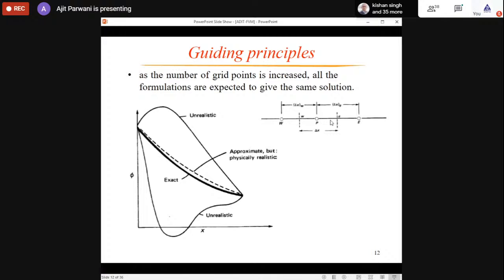So this surface is common to the adjacent control volumes. It means that the flux that passes from P to E should be received by E. That is, the flux at this surface should have a single value, not a double value. There should be a consistent flux at surface E, because it is common to both the control volumes.